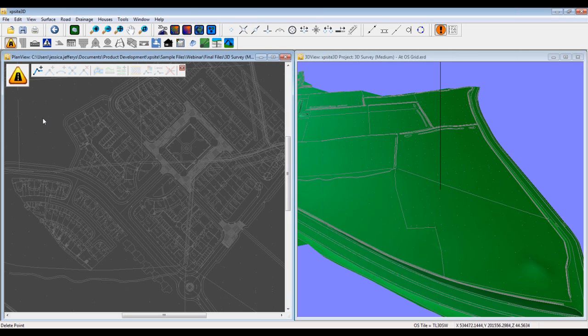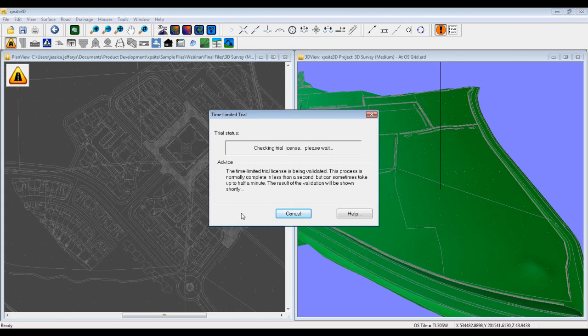So now we can begin our road design. And the principle we'll be following is setting up the road centre lines first, which are laid out on our drawing, and then applying road profiles to each centre line. If you don't have the luxury of such a detailed road layout, we do have construction tools up here which allow you to do things such as create a parallel or find the midpoint of a line and snap to those items if you have a little less detail.